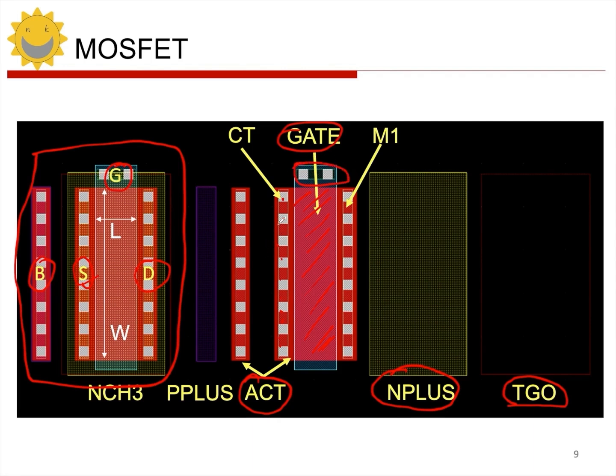That's fine. And don't forget about the substrate bias, right? Since it's an NMOS, its substrate is P-type. So first, we need to have a well region, and then we cover that well region with P+. Also, make sure to use contacts and metal to connect it out. So, with this metal, we basically connect it to VSS, right? With VSS, the NMOS is now essentially drawn up.